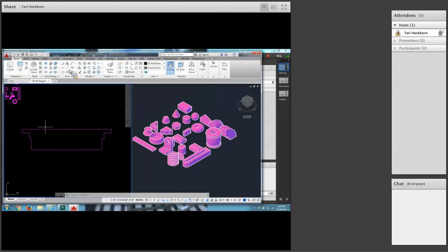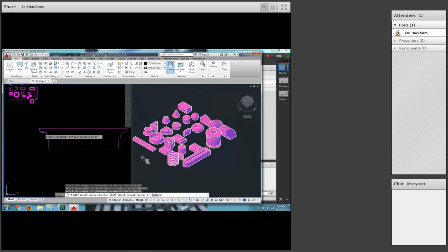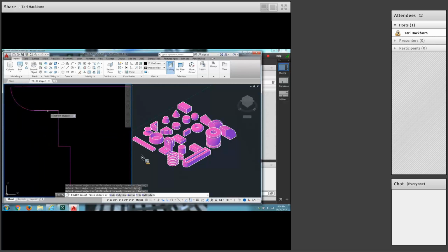It's kind of all squared in. This is actually my favorite piece of all the pieces. I love using the intersect command up here. It's all squared in, so it needs some fillets. Let's get our fillet. Give it a radius down here of 1. Okay. And enter. May as well select multiple. There's going to be a few of them. So this is where my radius goes, from here to here, and then from here to here. Nice shape, right? Same on this side, here to here, and from here to here.